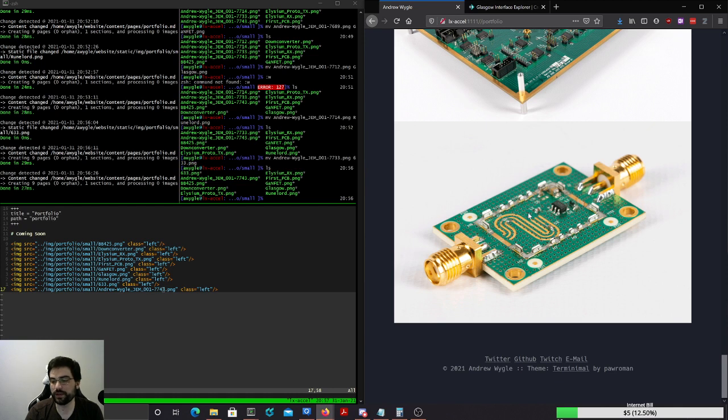The reason for this big long snaky trace is, first of all, this board's coplanar waveguide because it's basically impossible to get a good impedance match on something this thick if you try to do microstrip. So it's coplanar waveguide. The center is the conductor, and then the exterior is ground. And the reason that the traces are exposed and it snakes like this is because, frankly, I was never able to get the simulation of this LNA to match what the vendor specs said it should be.